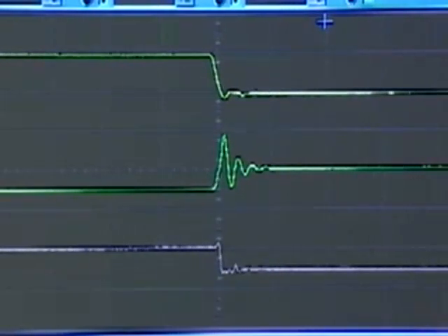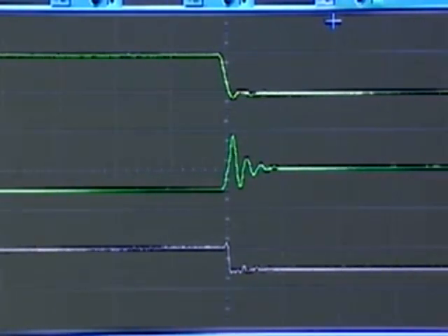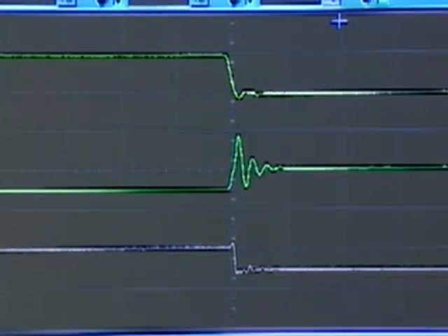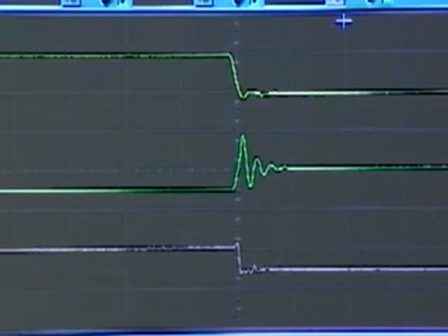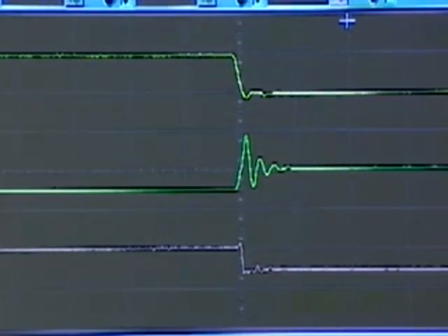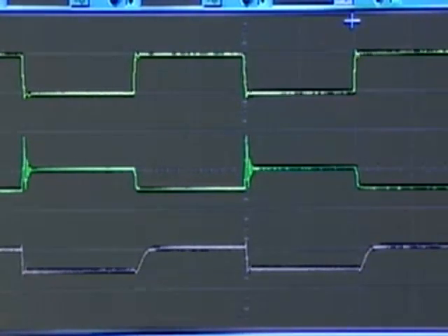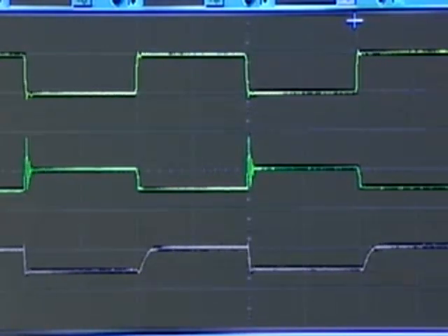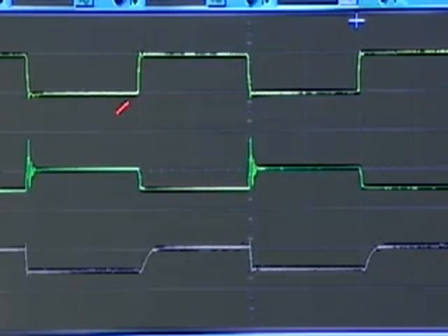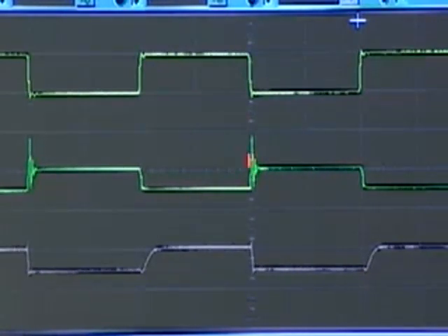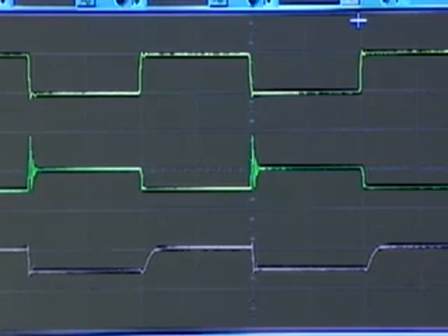Okay, and trust me, when I did some circuit designs myself a long time ago, I got nailed by that. I looked at my circuit, and I was noticing these sharp lines at all my transitions. Okay, when I looked at my scope, I expected to see nice little square waves, but I saw these nasty spikes sitting out there. And when I stared at it more carefully, those spikes are really sinusoids that seem to kind of get tired and go away. So those are nasty, those are real, and they happen all the time.